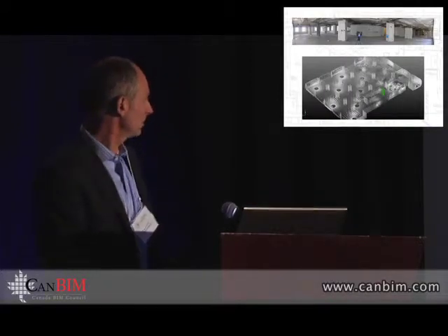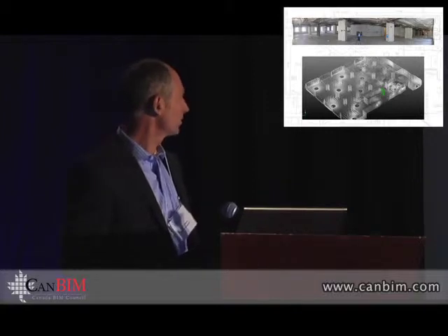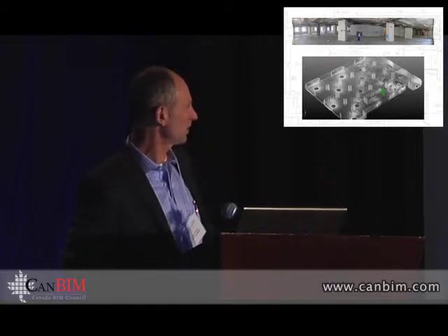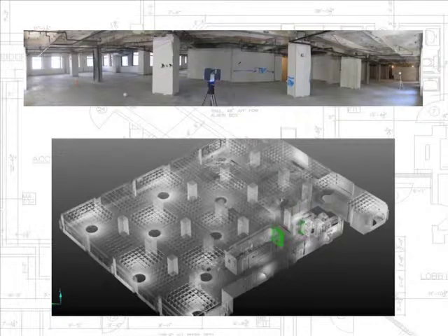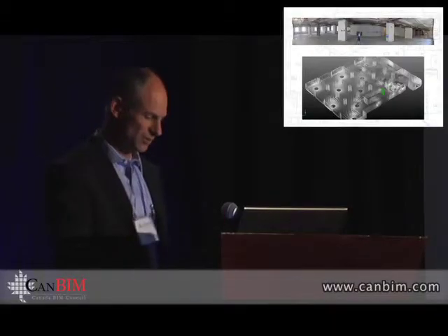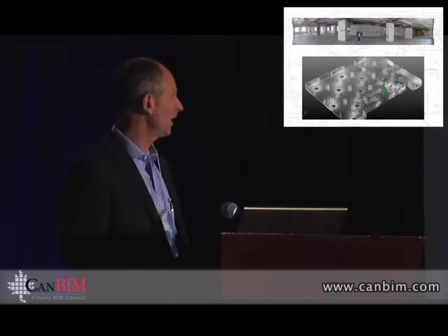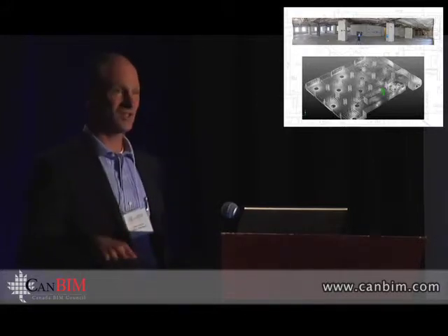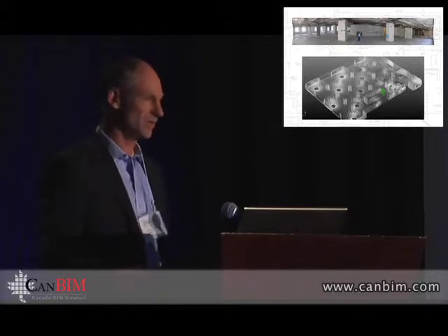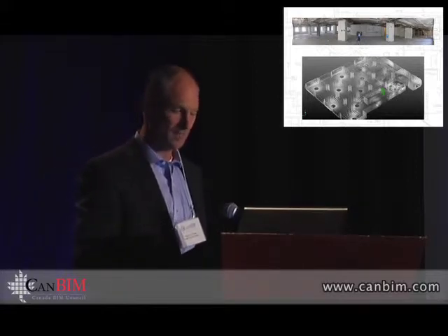That's just an example of an overview showing the picture where the scanner was, and then some of the positions. So the holes are the tripod locations on the lower picture there. So roughly 10 or 12 positions are required to cover something that's reasonably large. And I might add, reasonably sparse, too. So if there's a congested environment that you're gathering information on, then you're going to need more positions, because it is a line-of-sight data acquisition device.